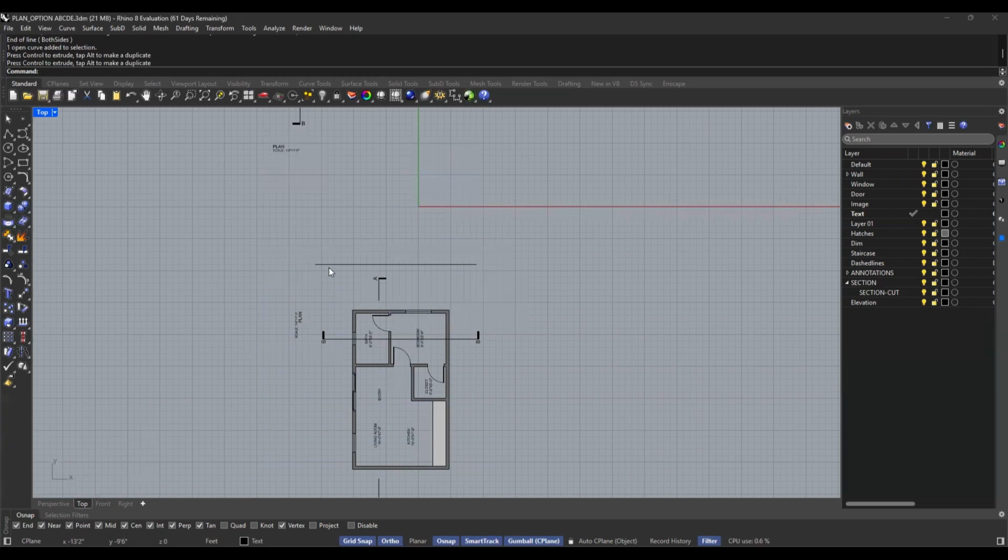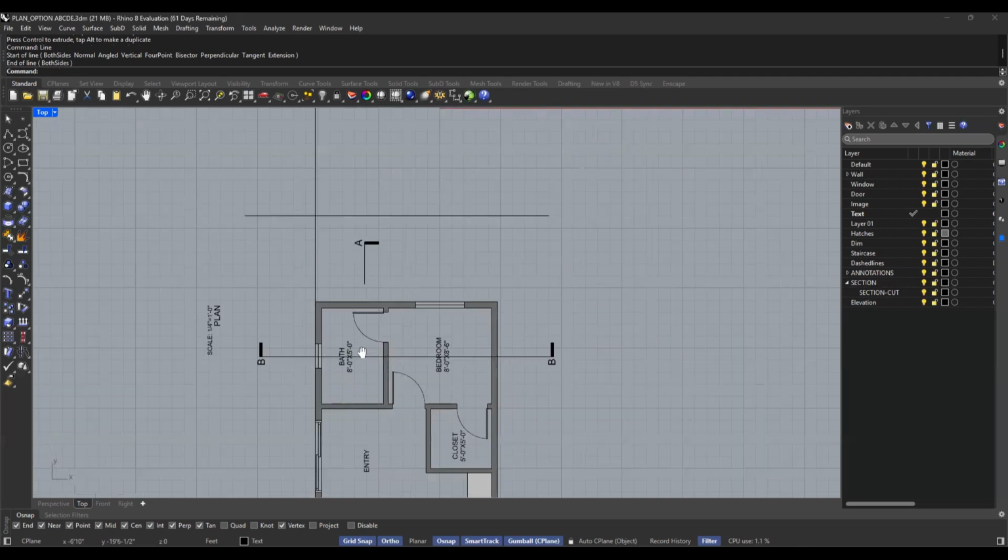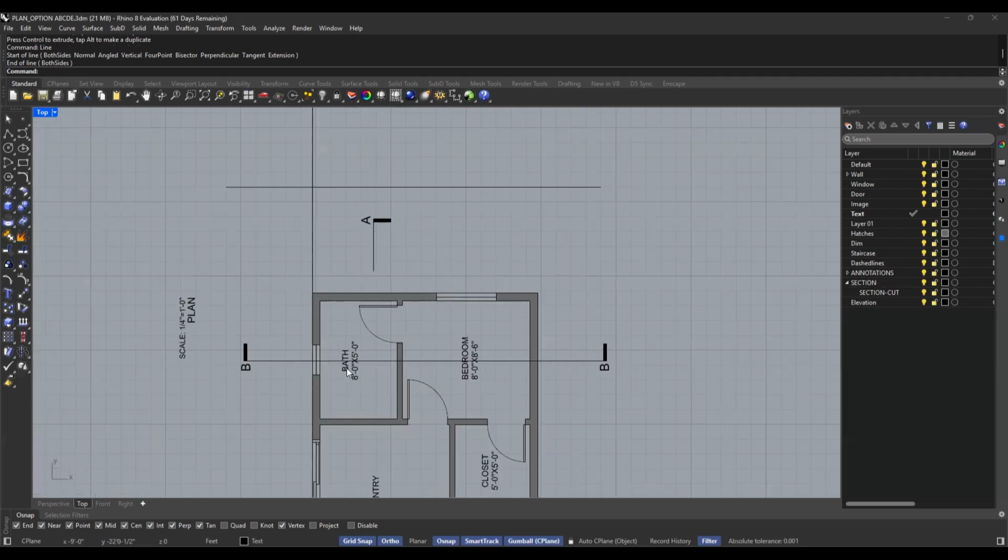So you have to draw one ground line, and then the next is I am going to project walls up, right? So use the vertical lines from wall edges. So type line, from here to here. And make sure about this: if you draw one line on your section marker, you will see where we have cut through the wall.